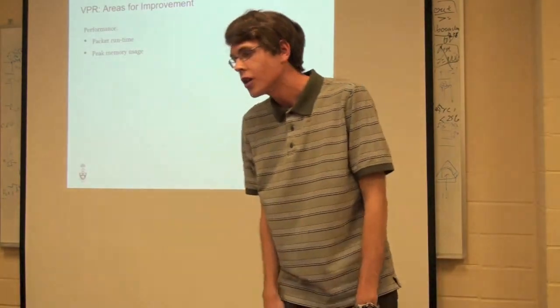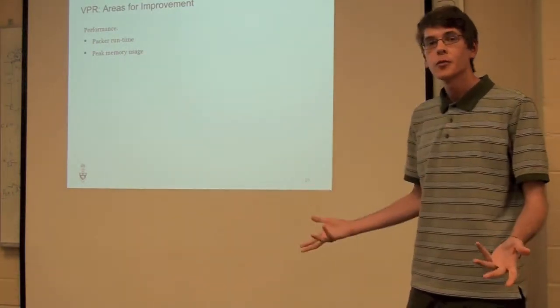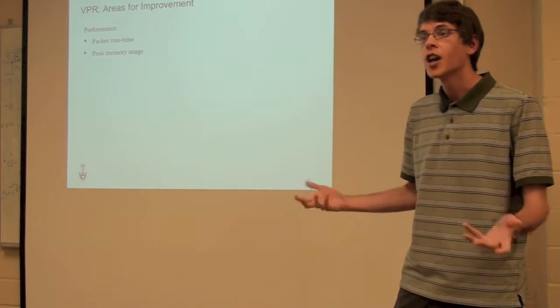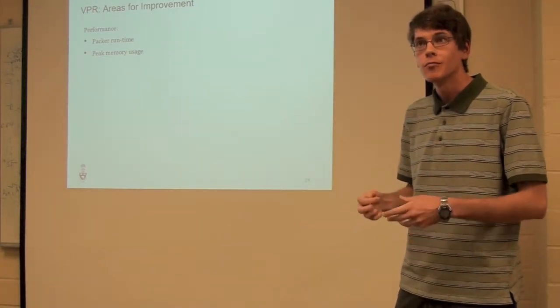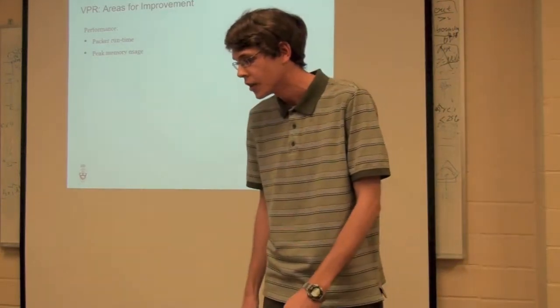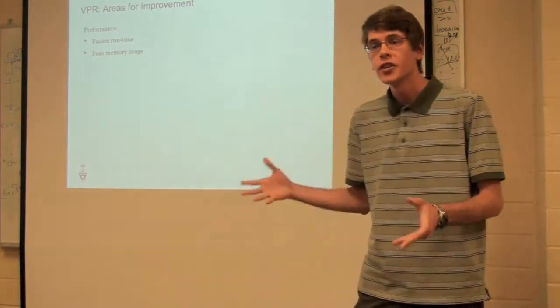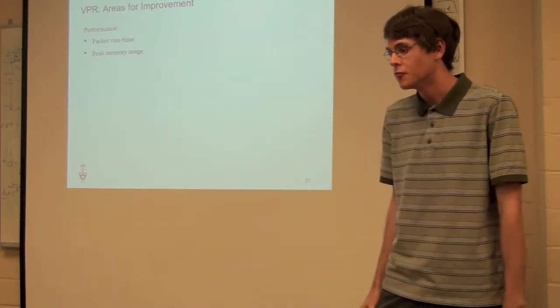So from this, we can draw a couple of potential things to improve in VPR. From a performance perspective, improving the runtime of the packer would be useful, because this might allow us to successfully run some of the larger benchmarks, which ran over 48 hours. It would also be useful to bring down the peak memory usage of the tool, because this would make it easier to actually run these benchmarks.